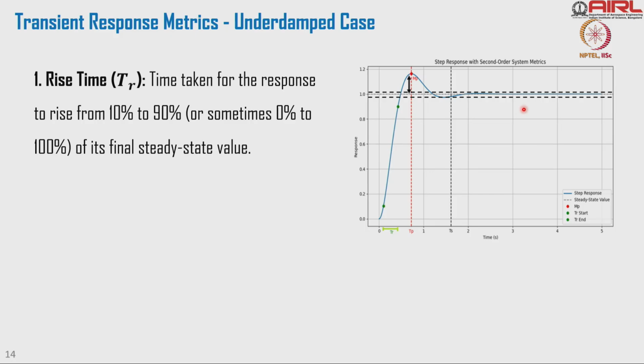I talked about this. If you want to go to the 5th floor, and the lift stops at the 4.5th floor, like a 0.5 meter error to the level of the floor, you can't go out. Or if it goes up also, that is a problem. So you need to know how to translate the user requirement to specification. Then you take a system, model it, look at the responses, analyze the responses, and then understand which response is not satisfying the requirement. And then design a controller in such a way that that has been taken care of. Not only that, the rest of the response also should satisfy. So that's what it's all about.